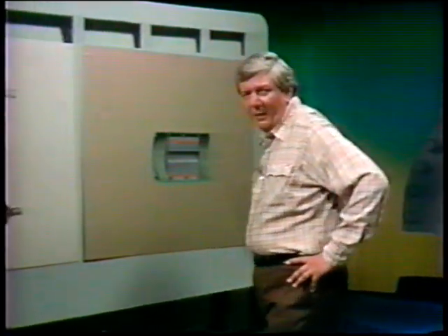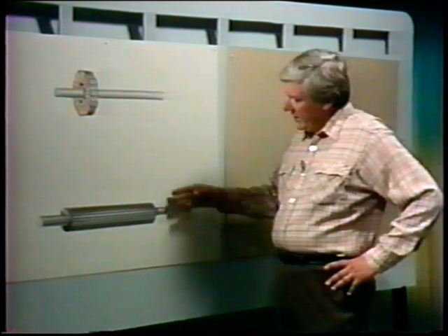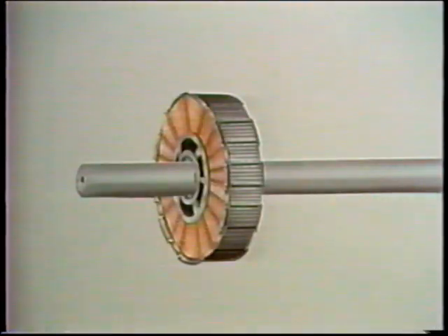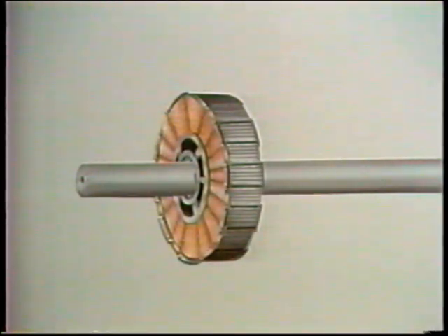Okay, we've seen that rotors in generators can have different numbers of poles. Now let's take a look at a couple of different types of rotors: salient pole rotors and high-speed or cylindrical rotors. A salient pole rotor has windings which are wrapped around metal pole pieces. A shaft supports the rotor assembly. Salient pole rotors are usually found in relatively low-speed AC generators. Their windings would be torn loose if they were used in higher speed situations. This is because of centrifugal force and other stresses that occur at high speeds.